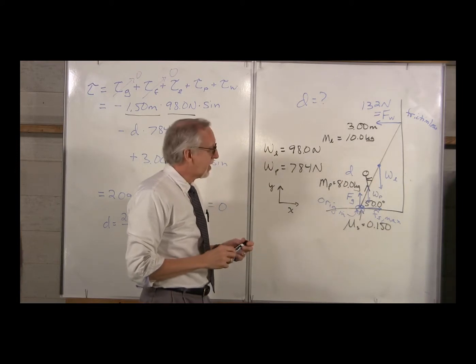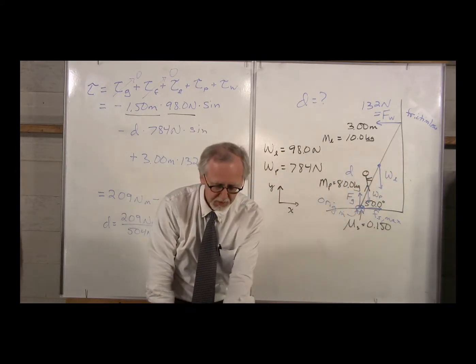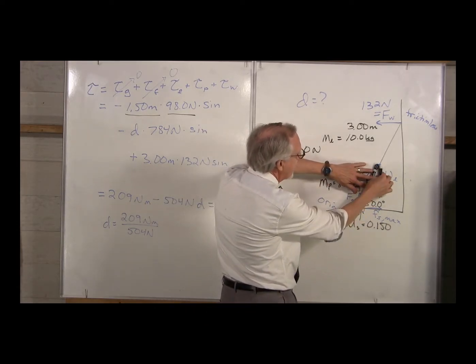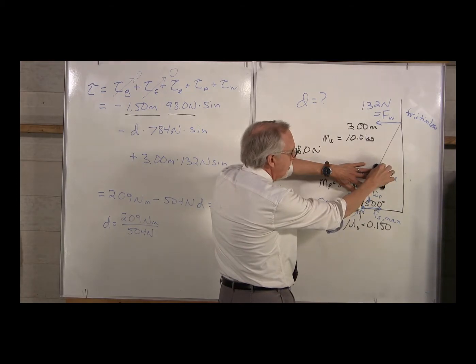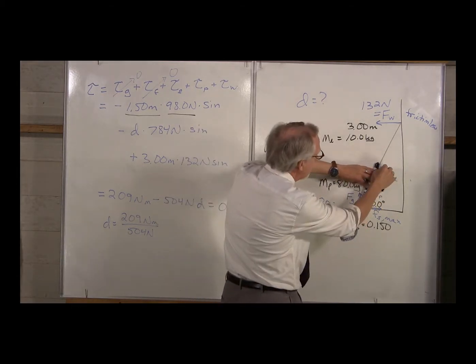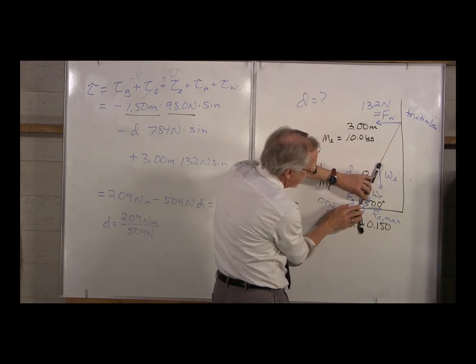Let's be very, very careful. Here's the weight of the ladder. Here is R. Here's the weight of the ladder. We want to find the angle between them. How do we find the angle between them? Tail to tail. We'll bring the weight of the ladder down here. We want the angle between those.